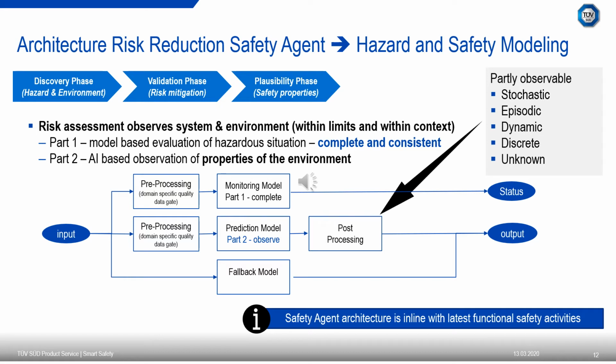For any conflict between the monitoring and the prediction model, we have the classical safety function and we jump back as a fallback into the functional safety operation and the safe state. The strong benefit is obvious. In case we can guarantee that no person is detected in the specific dangerous zone, the possibility of avoidance of the risk is 100%. Risk reduction is not required. We don't stop the machine, productivity goes on.